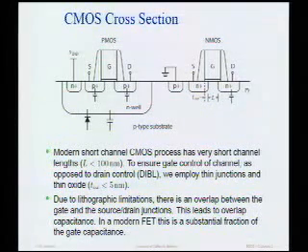Finally, some other non-idealities. Source and drain junctions are reverse bias junctions, right? So they have capacitance, reverse bias diodes. On the drain side in particular, if I ground my source, I'm going to have a capacitance at the output. You guys have studied that in all the courses you've taken, so you know that very well. What's another non-ideality in the FET? Anybody? Exactly, the body effect.